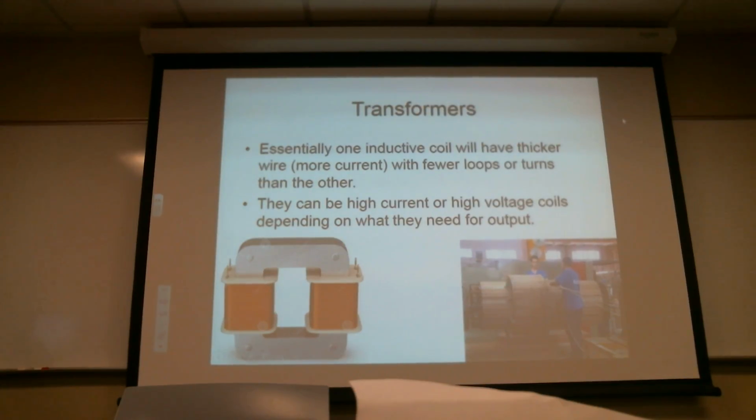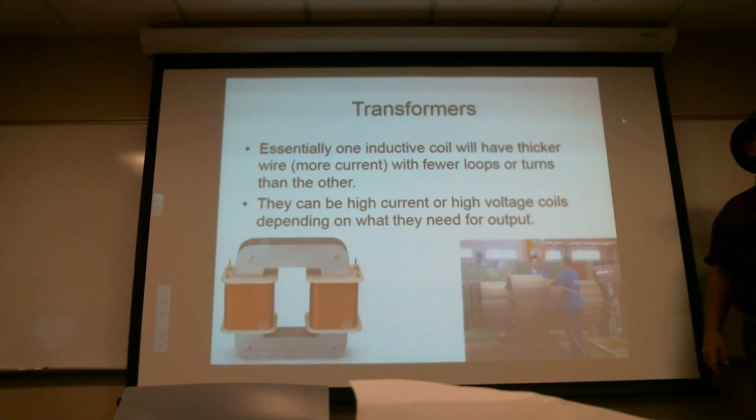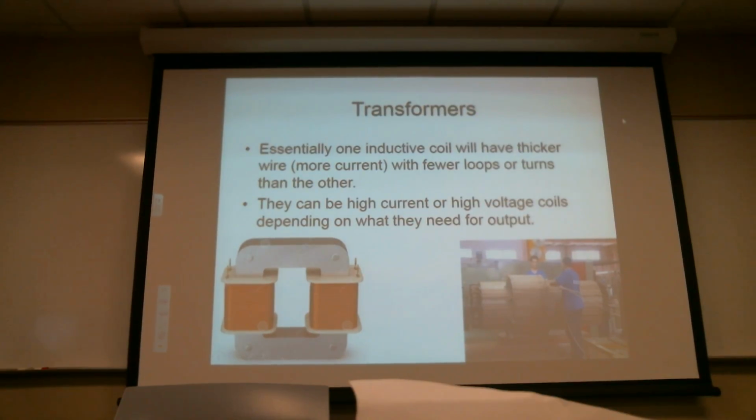Now another one that's being designed, these two guys building up this big transformer here, that puppy's a serious transformer. That's a big spindle that once they've done wrapping it, and a bunch of plates that secure it all together, the inner core comes out and they have this big huge transformer that they can then put whatever core they want in. It's entirely likely, given the multiple wires that are going in, that the different windings are all wrapped around and wired in the same bundle. That's perfectly acceptable. As the magnetic field is induced around one, it's going around the other. We do this very, very commonly with ignition coils.